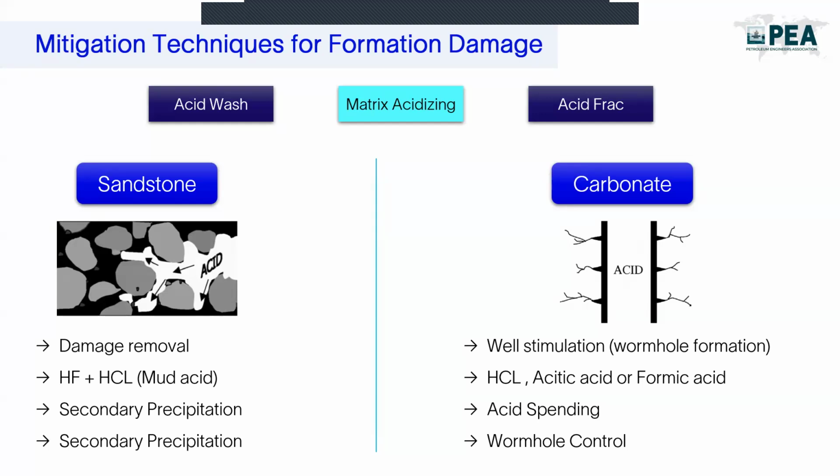So if there is damage, either clay minerals or minerals due to drilling or completion, it will help us to remove this damage. But if there is no damage, if there are no clay minerals, in that case, it will not add any solutions. So that's why it has been said that sandstone is a damage removal. Matrix acidizing in sandstone is only a damage removal rather than a well stimulation.